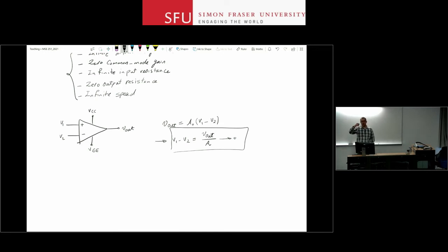If you make a change in V1, the op-amp will go through, whatever magic that is happening inside, and ensure through the circuitry that is around the op-amp, you usually have a resistive network, it ensures that V2 follows V1. The difference between these two will be very, very small. Usually, practically, it's not measurable, so it is 0. That is one interesting conclusion.